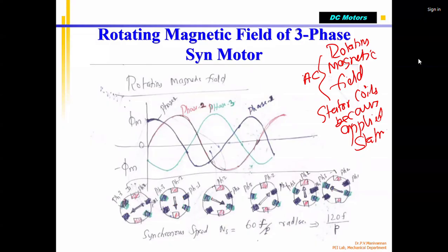So what it does is, initially the rotor was like this. I told you, before you apply the voltage, the rotor can be in any position. For example, it was like this. You have not applied any voltage to the stator. The rotor has DC voltage applied; this is north pole, south pole. Once the AC voltage is applied at time t equals 0, the voltage starts increasing. Everything is varying. But at this time instant, the blue has the maximum, for understanding purposes. So this is pulled, and it aligns with this at this time instant.